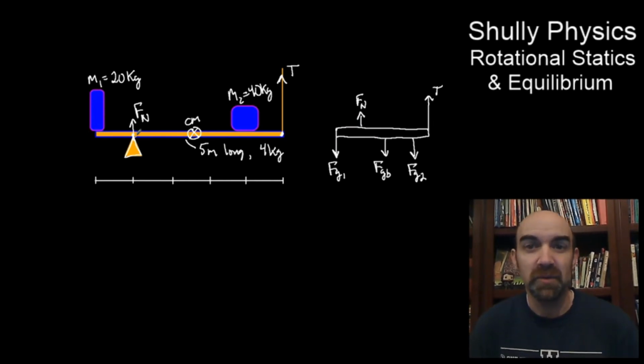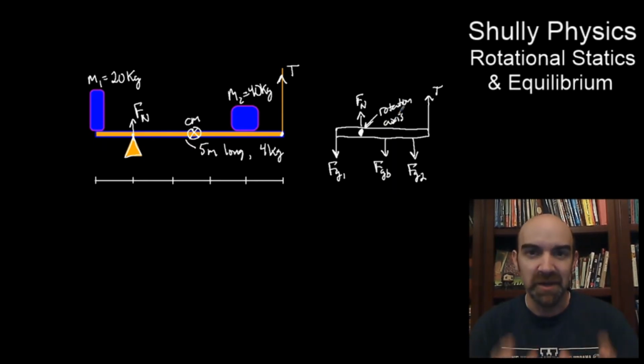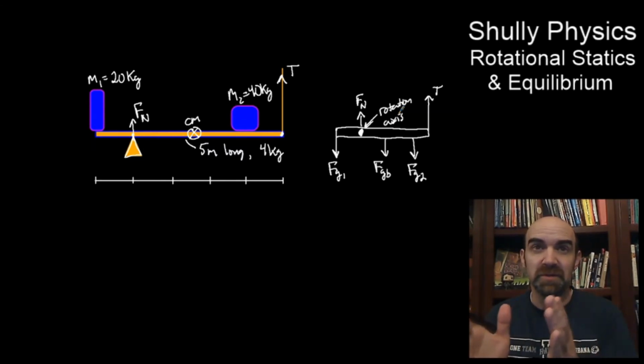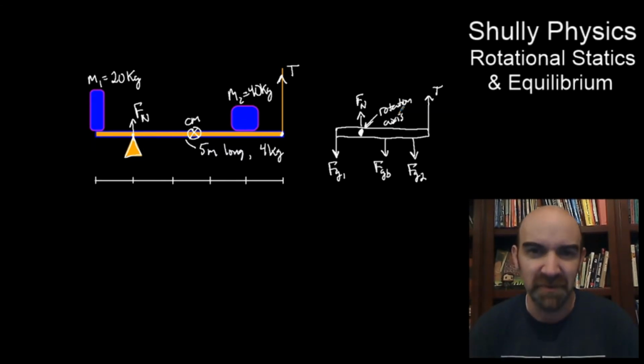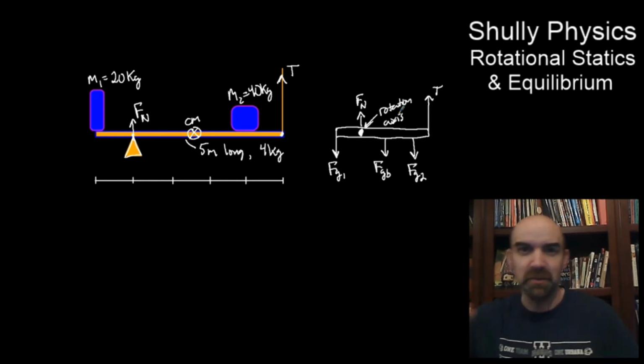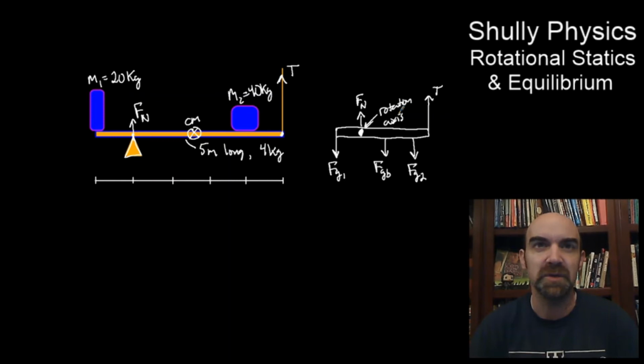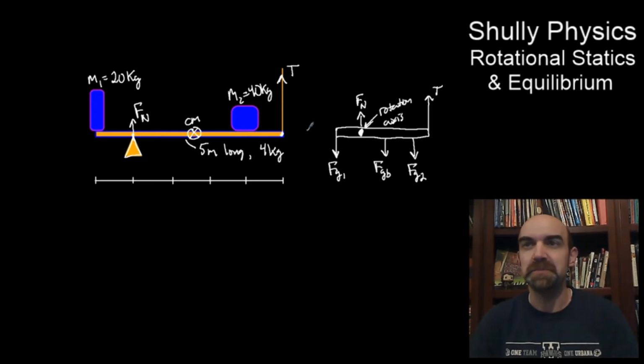And when it rotates, this is going to be the point of rotation. Okay, this is the rotation axis. It's often very useful and important to take note of where the rotation axis is. That point is where it's being held. It's not allowed to translate through that point. There are no side-to-side forces, so this board won't slip off. It'll just tend to rotate, at least at first. Of course, when it hits the ground and bumps, it might actually rotate a little bit off that fulcrum. But this initial rotation will be about that point because it's not free to translate up or down.